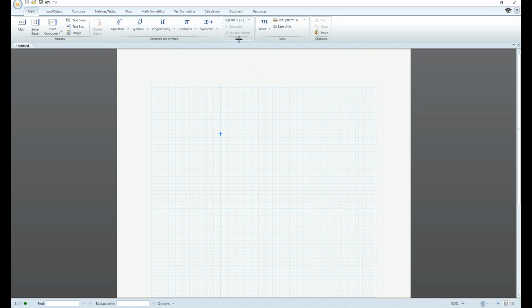Then we have the style, which is used primarily to manage the view, and units. Mathcad really allows us to manage our units more than any other program. The unit manager does have its default unit system, which is right now set to SI. But for any measure or any variable with a defined value, we can choose what units are applied to that value within that value's definition. This means that the units are intrinsically tied to that variable's value.